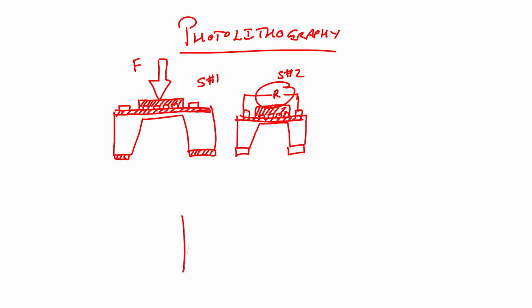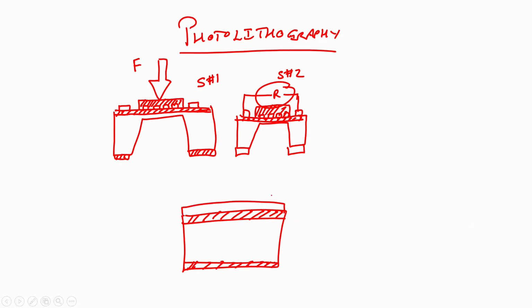The process is like this: there is a silicon wafer, then we grow oxide, which is our silicon dioxide. The next step is depositing a piezoresistive material on this oxidized silicon substrate, and then I perform photolithography, so that I have the pattern that I am interested in.